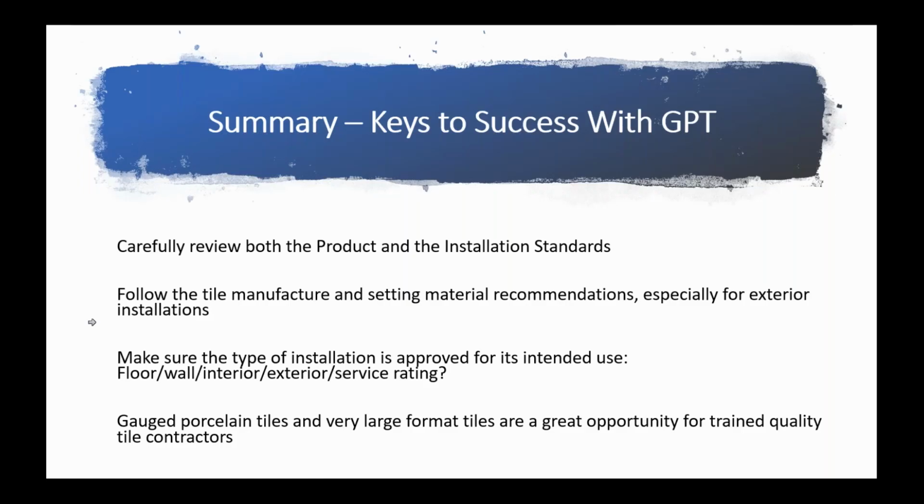All right, we're going to wrap this up. In summary, carefully review the product and installation standards. I strongly suggest you go to the TCNA website and in the publication section and get those standards if you're doing a gauge porcelain tile installation, interior or exterior.